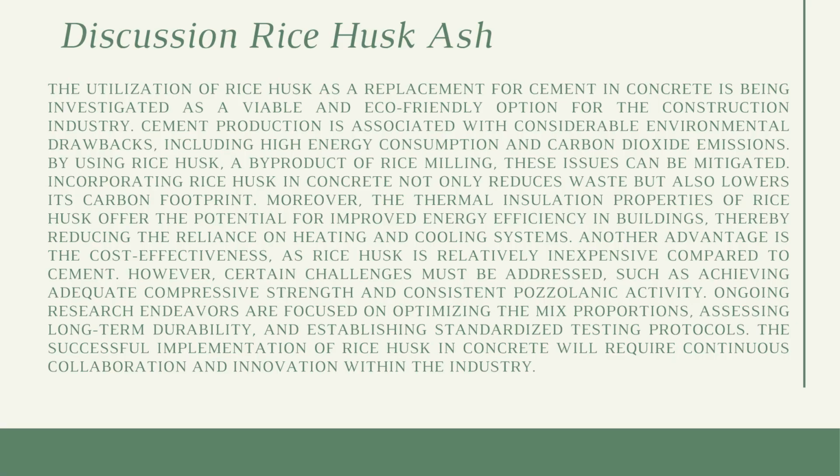Based on the discussion, rice husk is a viable and eco-friendly option for the construction industry. Moreover, the thermal insulation properties of rice husk offer a potential for improved energy efficiency in buildings, thereby reducing reliance on heating and cooling systems. However, certain challenges must be addressed, such as achieving adequate compressive strength and consistent pozzolanic activity.